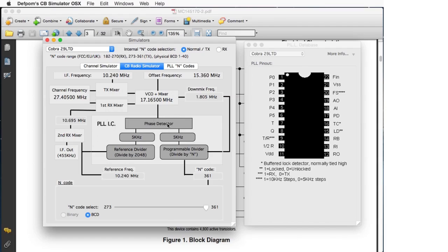phase detector correction voltage. So the phase detector output is this pin here, pin 7. That's what PD means, phase detector. And that's the correction voltage. And that downmix frequency coming in, I keep saying FN, well that's the FN pin there, frequency in. That's what that stands for. And that's all it's doing, is correction voltages. So it's got to be somewhere between, in this case, VDD and VSS, 0 volts and 5 volts. But the closer to the center of that range, the better.